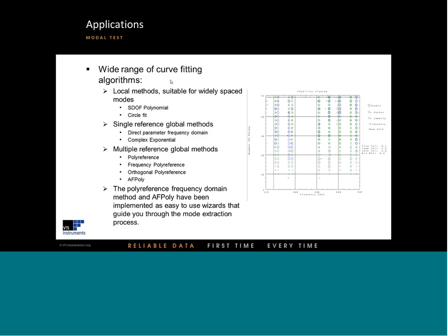And finally, and probably the most commonly used, the polyreference global methods. These include a time domain polyreference, a frequency domain polyreference, orthogonal, and the AF poly, or alias-free polyreference, from ATA Engineering.